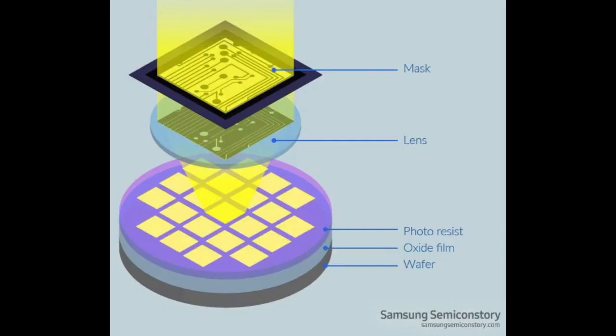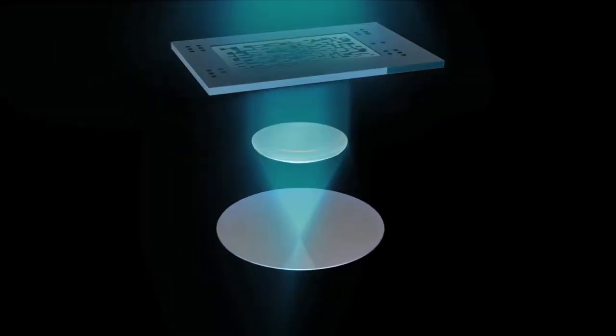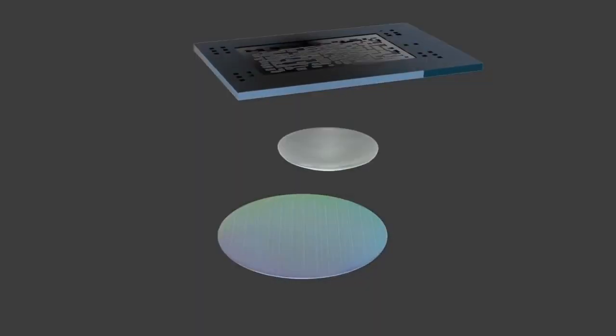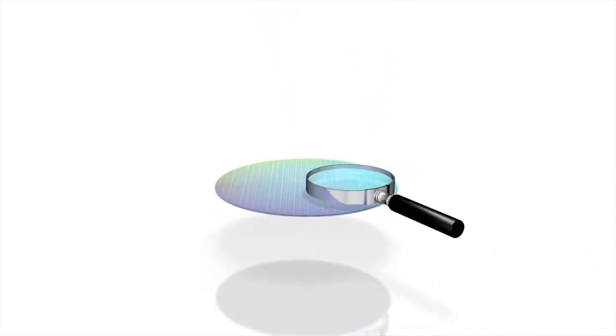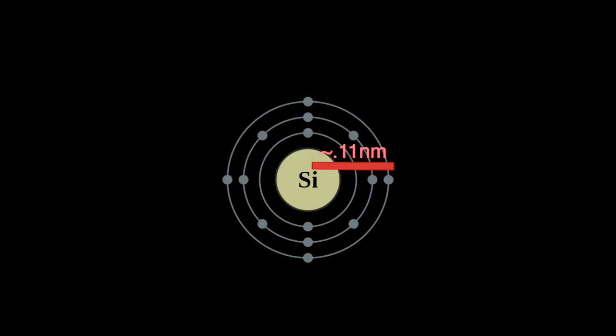Photolithography is Greek for writing on stone with light. Etching designs into substrates with light templates is a common technique in small-scale electronics manufacturing, where the patterns that are carved require levels of precision that are measured in the scale of hundreds or even dozens of atoms in width, as in computer chip manufacturing, where the functional components can be 10 to 50 nanometers across. To give a sense of scale, a silicon atom has a covalent radius of about 0.11 nanometers.